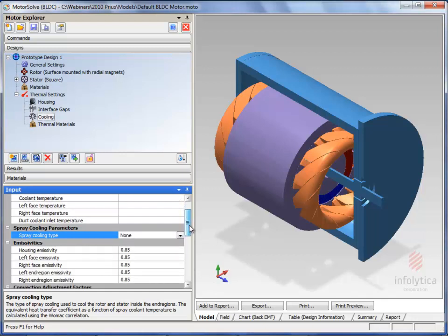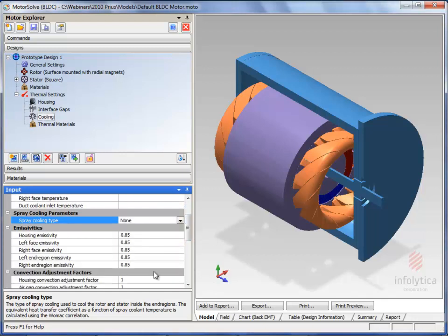Now I mentioned to you that there's also thermal radiation effects. And there's a notion here of the full control or the full representation of radiative physics known as emissivity. The default here is a factor of 0.85, and you can adjust these. There are certain things that change emissivity. Some of these things could be surface roughness or smoothness. It also could be the color of the paint and/or the sheen or glossiness of the paint.